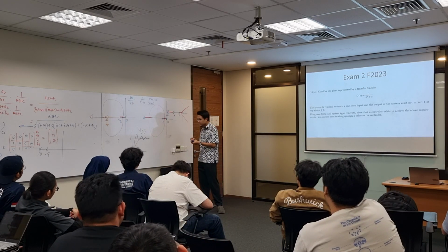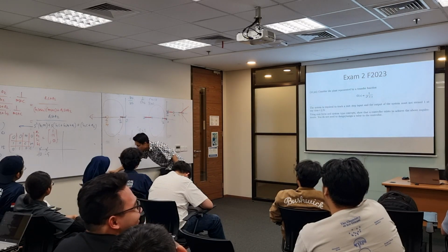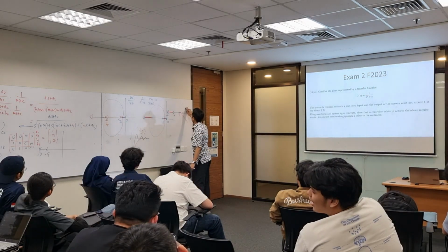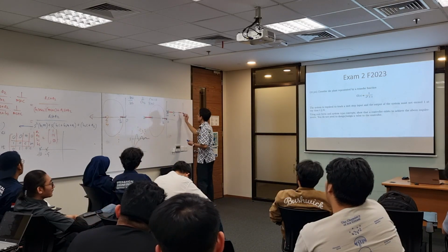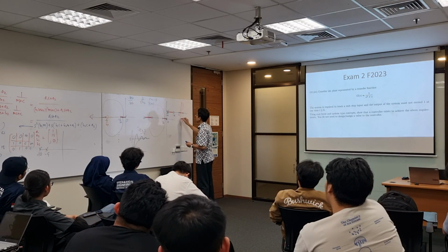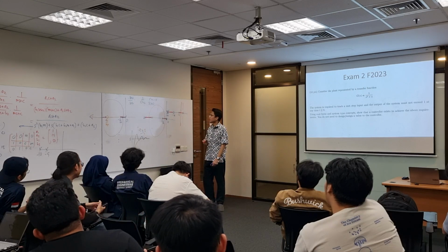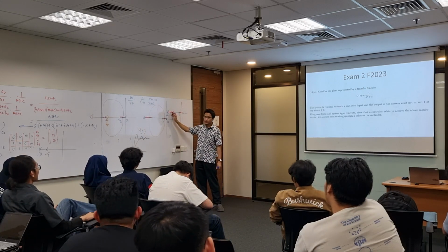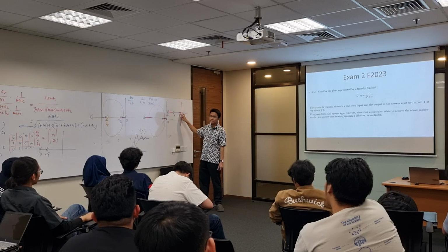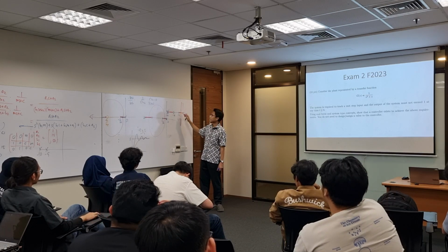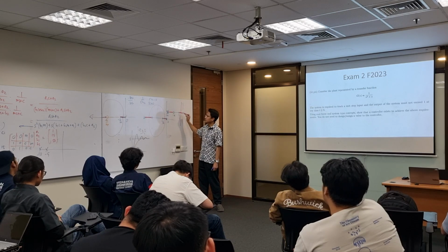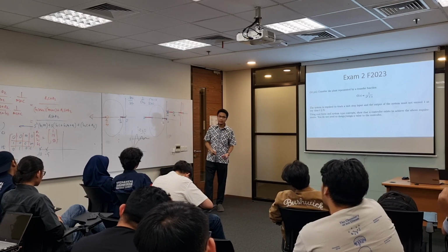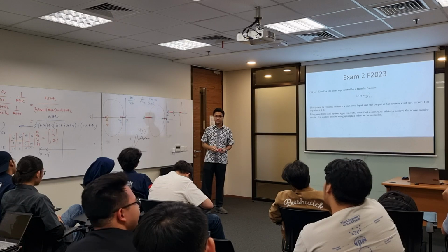No, we have 2 asymptotes. Sorry, 2 asymptotes. Then it goes up. Sorry, not go here, but it goes up. It should go up. Okay, this will be the non-dominant pole. Over here is your dominant pole. So if you place your poles over here and over here, then you can satisfy zeta greater than 1.